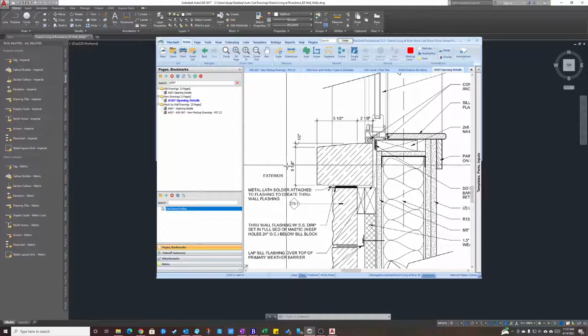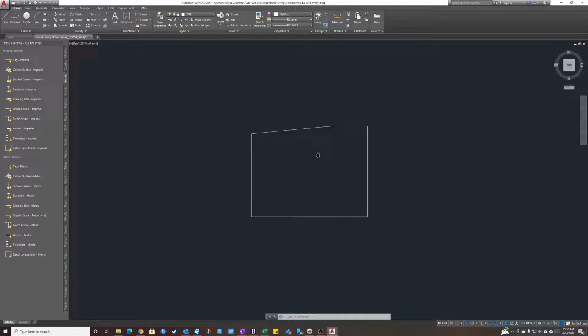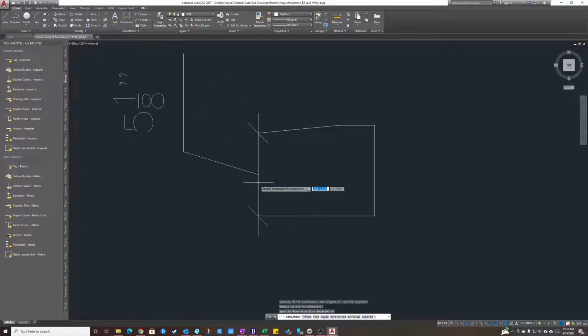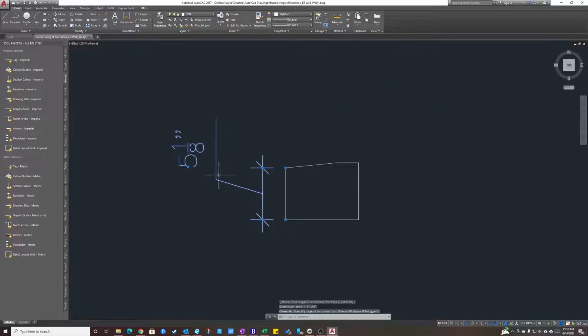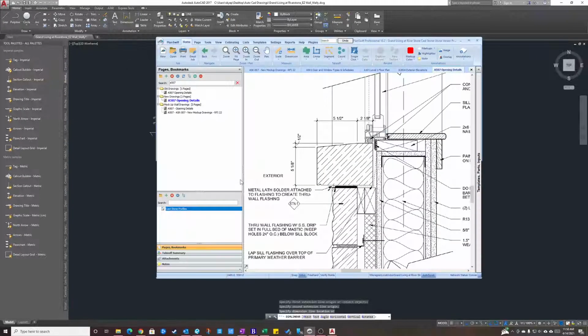We can verify these dimensions as well. It's 5 1/8. Yeah, 5 1/8. And then the slope, lineal, you click from that part here to this part here. You drag over. So half an inch. Yep, half an inch slope.